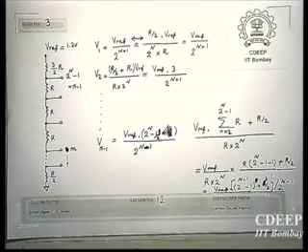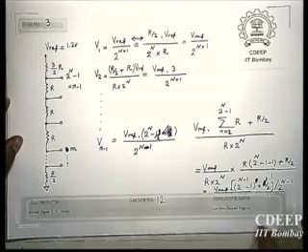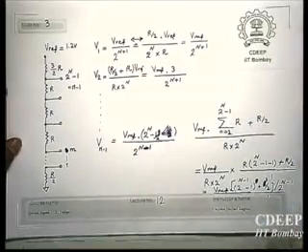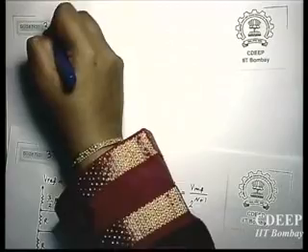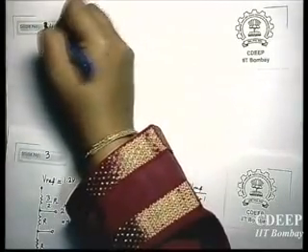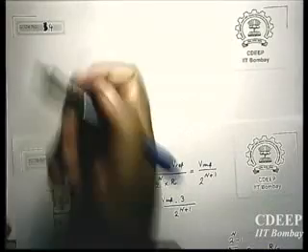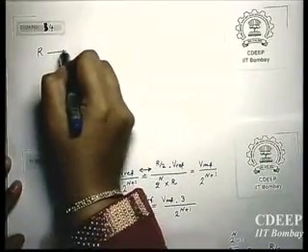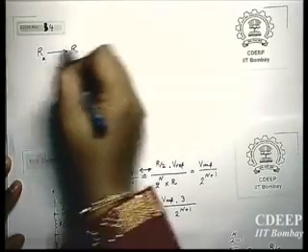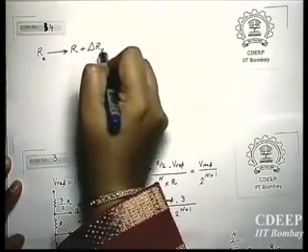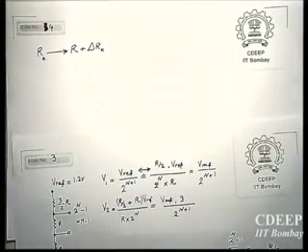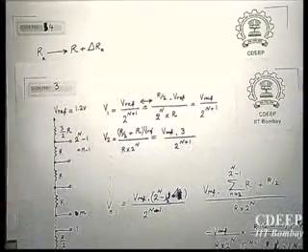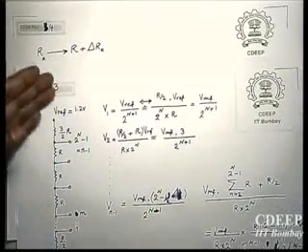Okay, anyway, so these are reference values. Now we apply them to a set of comparators. So till now we consider all are the same. Therefore, the first point regarding non-idealities, a very interesting point, okay, I will stop it, just I tell you. Now what if every resistor changes by some particular value of R plus delta R? Suppose simply you have a simple resistive divider. You want to look if there are mismatches between resistors, what will be the worst case?